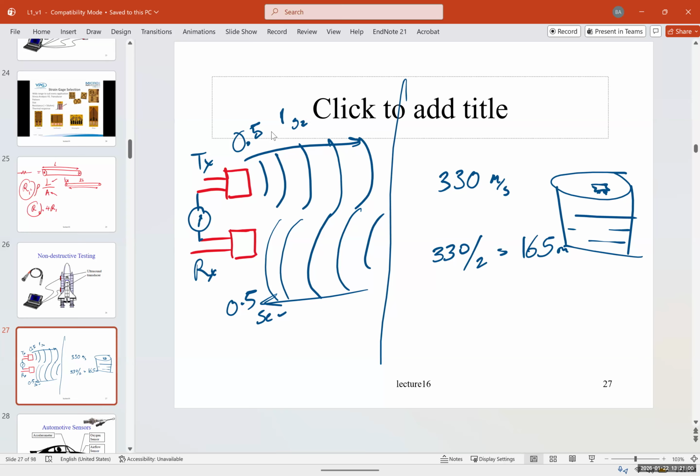Now they do it automatically, so they measure temperature and correct the error if you want something very accurate. If you don't want accurate, if you just want to measure something, like a scale, or the distance between two walls, you're a carpenter or something, these are not very accurate, because depending on the temperature and humidity, there's error on it. So that's the reason they use infrared or LiDAR. But if you just want a park sensor that gives you a beep so you know you're close to something, 1 or 2 centimeters or 10 centimeters doesn't make any difference.